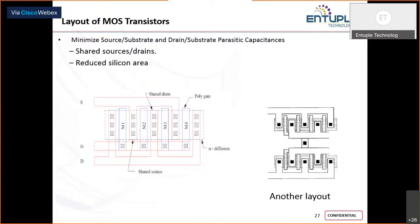These are the basic techniques to minimize the source-to-substrate or drain-to-substrate parasitic capacitance. We have discussed how to reduce the parasitic resistance, basically the series polysilicon resistance and also the channel resistance. Now we are discussing how we can reduce the source-to-substrate or drain-to-substrate parasitic capacitance. For 180 nanometer technology, your source and drain will be in metal one, so between metal one and your substrate there will be a capacitance, obviously. How can we reduce that? One of the techniques is to use shared terminals. You can use shared sources or drains, which also reduces the silicon area.